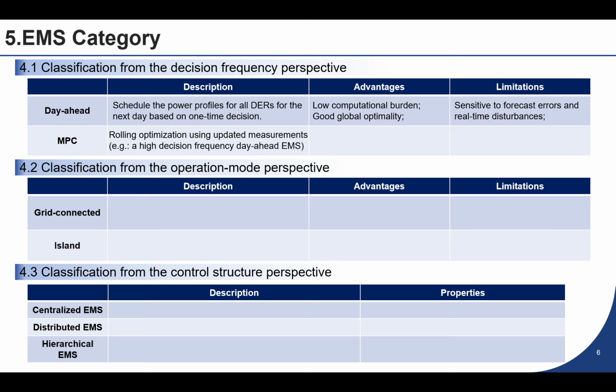Next, the MPC-based EMS performs rolling optimization by frequently updating measurements. It provides strong adaptability to real-time changes, but this comes with a significantly higher computational cost. From the operation mode perspective, EMS can be classified into grid-connected and islanded versions.